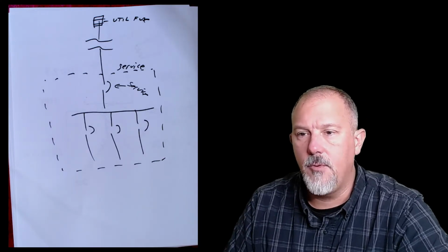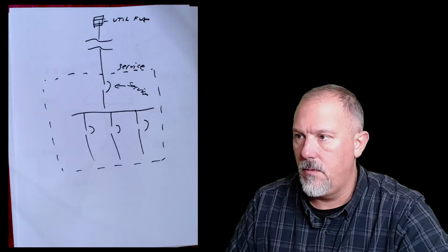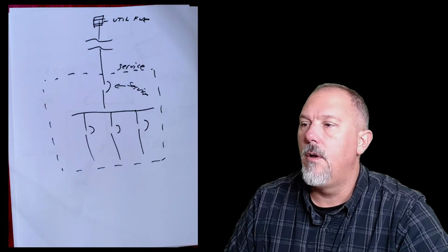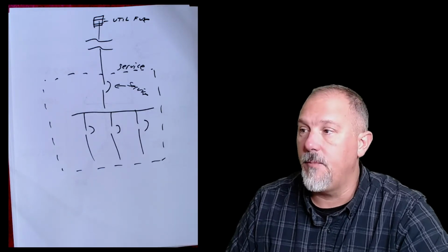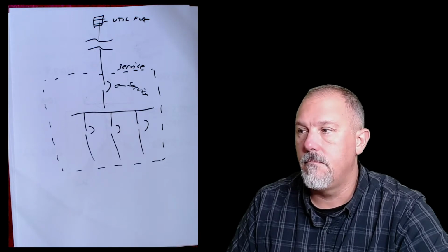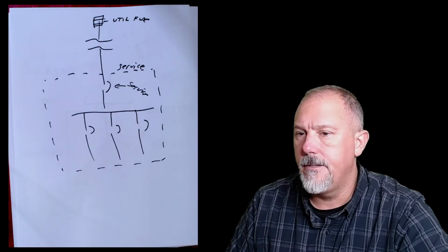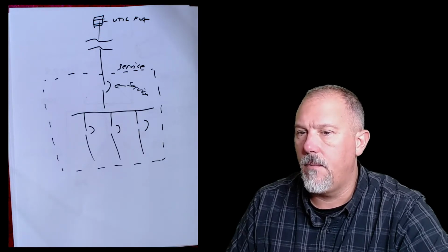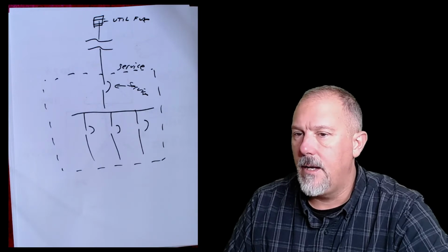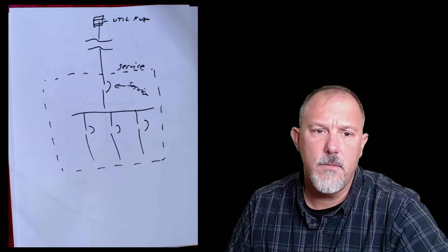B tells me the label must be in accordance with a standard. It says an arc flash label. The arc flash label shall be in accordance with acceptable industry practice. And then they give you some examples. Any additional info. It doesn't require any additional info. Right. I mean, you just need an arc flash label.